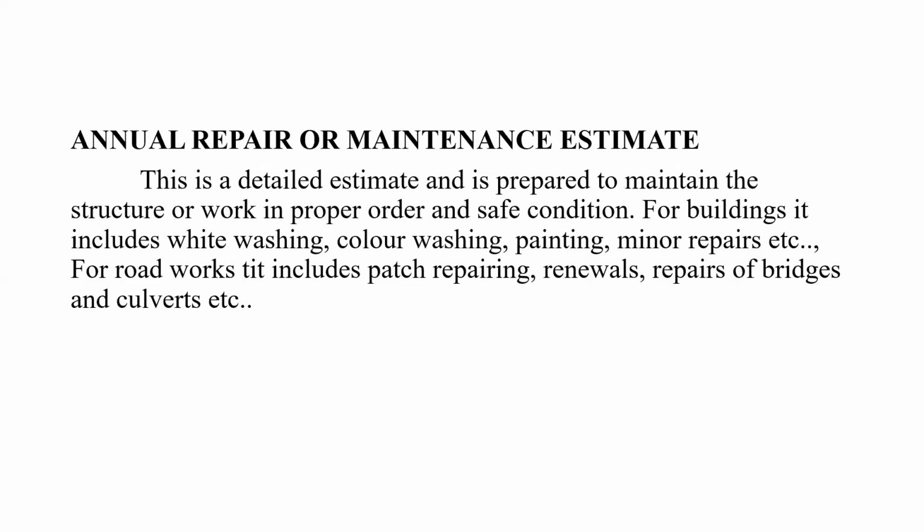Next, annual repair or maintenance estimate. It is a detailed estimate, and it is prepared to maintain the structure or work in proper order and safe condition. For buildings, this includes whitewashing, color washing, painting, and minor repairs. And for road works, it includes patch repairing, renewals, and repairs of bridges. Further, there may be a special repair estimate, monsoon damage repair estimate, etc., which we can go over.